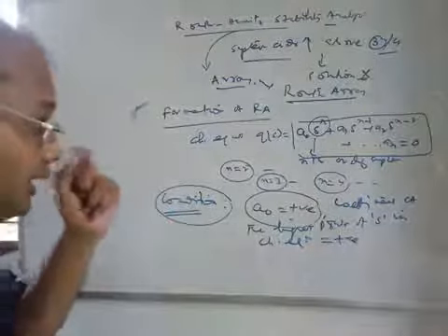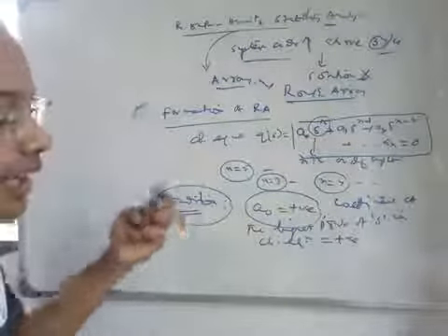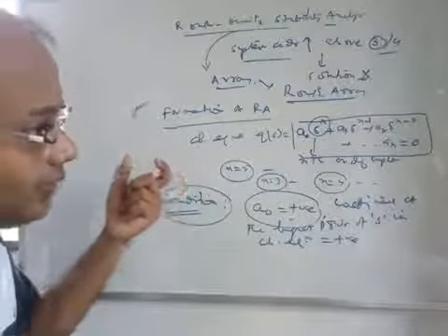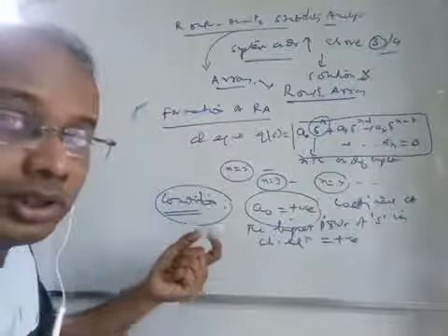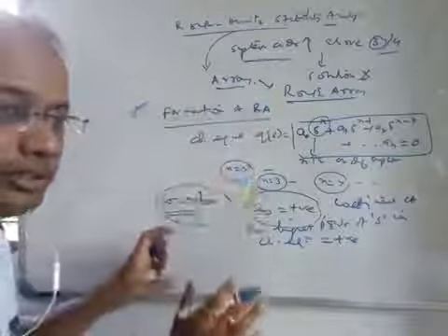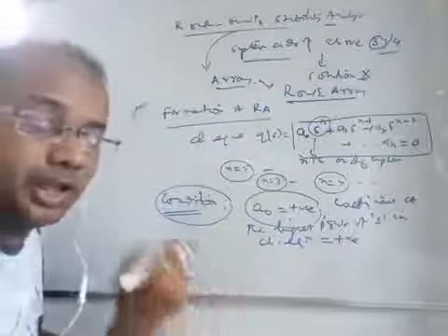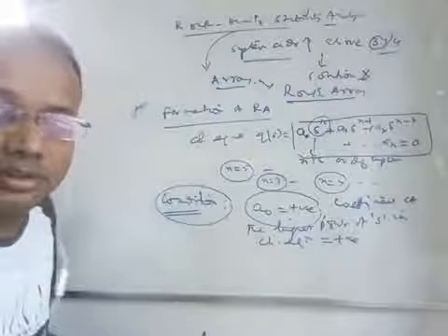So we are not generalizing it. We are going to take one example of how, from the characteristic equation given to you, you can get the completed Routh array, and after completion of the Routh array, we will consider how to get the stability from it. Okay.